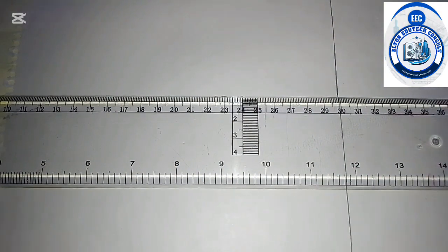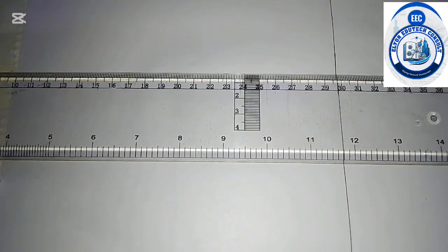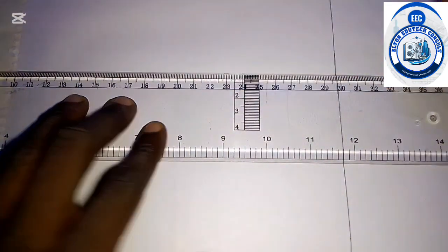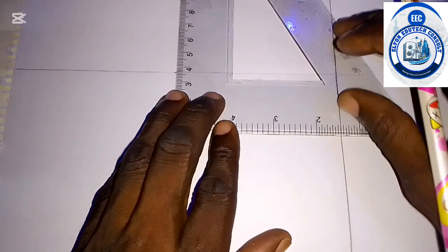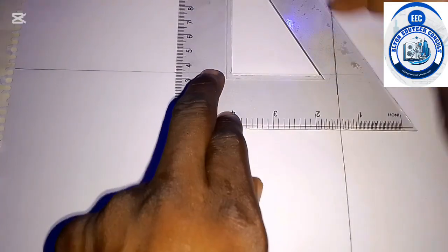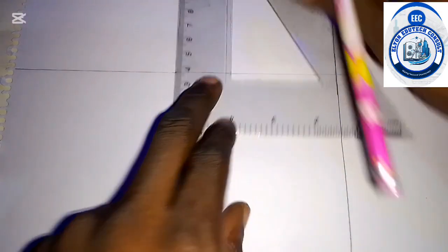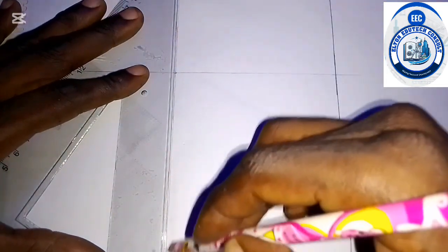So what we do here is that you are going to draw this line as center line. Then we are going to pick a point that will serve as the center line, vertical line. Okay, so we are going to be getting the minor axis and the major axis first. So you have this line, produce this line down this way. Okay, now we are told that the major axis is 130.